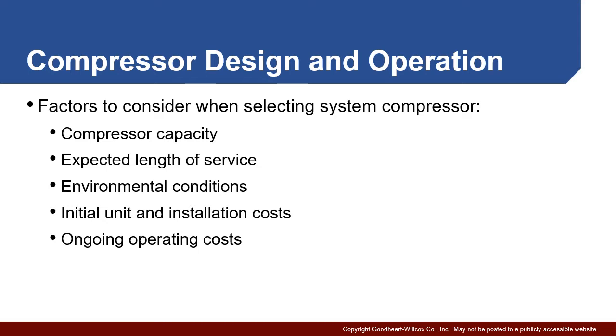In terms of the quality of the compressor, you definitely want to look at how long you want it to work, right? There are various qualities of compressors out there. A better quality compressor will hopefully have a much longer service life. Obviously, the environment that it's going to run in is going to play a role. The fact is, we have compressors that can handle dirtier environments. We have compressors that are built for higher elevation environments, etc. So you need to look at that temperature, pressure, different types of contaminants, etc. How well your compressor is going to be able to withstand those issues.